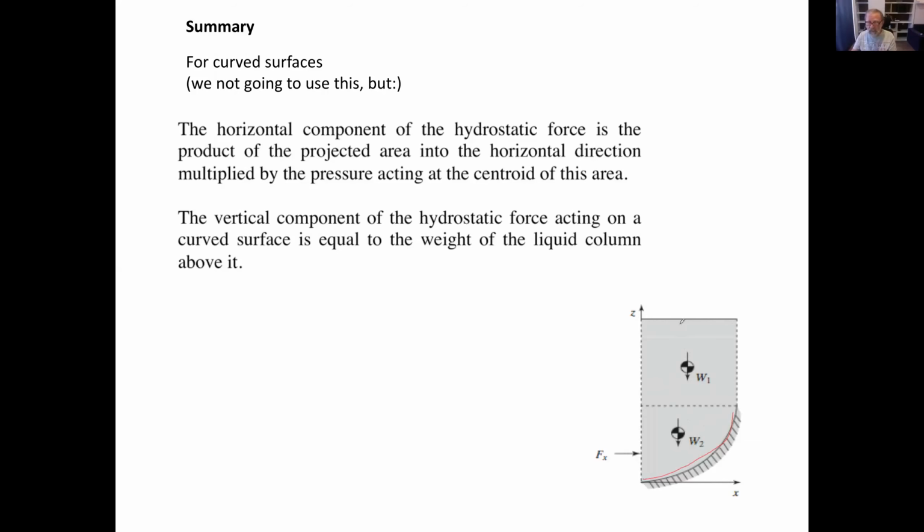then you can just simply take the weight of the liquid above that. That's going to be the force in that direction. If you want to find out what is the force in that direction, then you can have the projection. And then the pressure distribution looks like that. Okay, I don't want to spend too much time. It's the centroid of this area. And then the force in this direction is going to be the average pressure at that particular point. And that's very simple. Otherwise, you have to do integrals on curved surfaces, and then you're going to get scared.